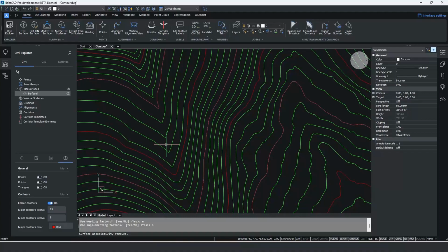triangles that it can. If we didn't do this and just treated these polylines as break lines, BricsCAD would simply triangulate points together by nearest neighbor. And what would happen is you'll see a lot of contours cutting across the end, and you would lose this bulge or the definition of that ditch or valley.